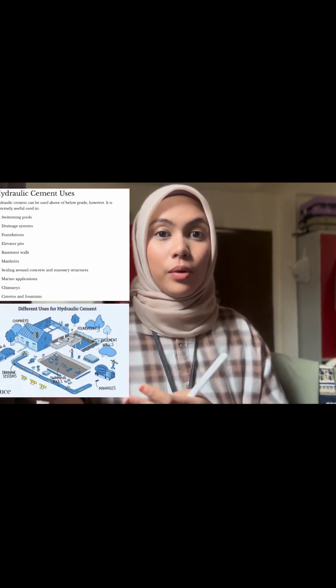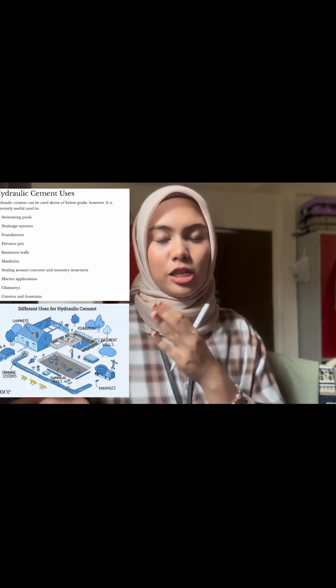Hydraulic cement is exceptionally suitable for projects that require speedy setting and less curing time. However, it gives only a short window of time to work with it before it solidifies. So, it is recommended to apply hydraulic cement only for projects that can be done in 5 to 10 minutes, with a moderate amount of cement mix produced at one time. This is some examples of hydraulic cement application.